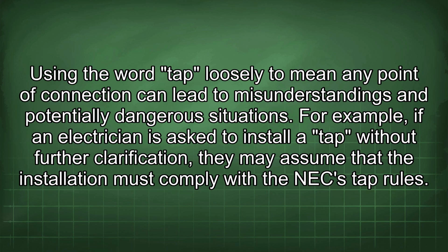Using the word tap loosely to mean any point of connection can lead to misunderstandings and potentially dangerous situations. For example, if an electrician is asked to install a tap without further clarification, they may assume that the installation must comply with the NEC tap rules.